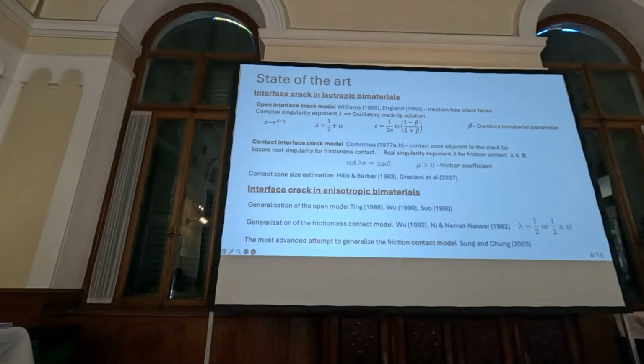To avoid this unpleasant feature of the oscillatory crack tip solution, Comninou proposed a contact interface crack model. She considered a contact zone adjacent to the crack tip, and she obtained a square root stress singularity for frictionless contact, but a real singularity exponent different from 1/2 for frictional contact.